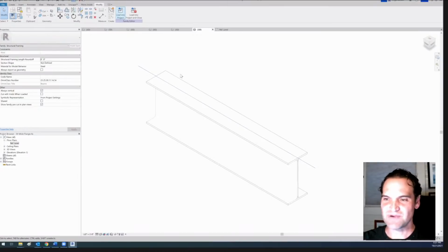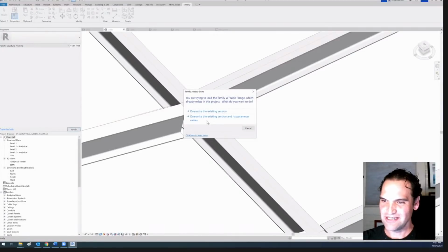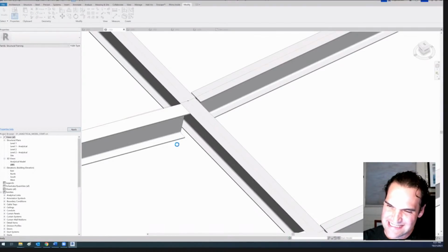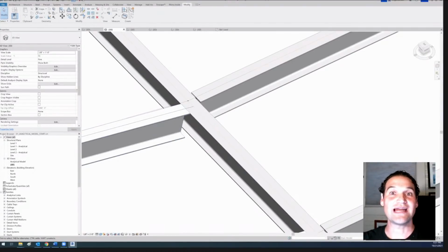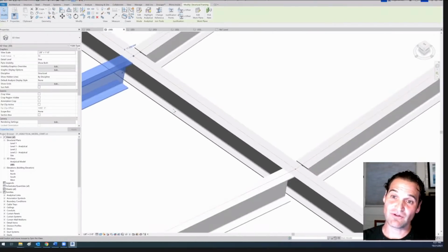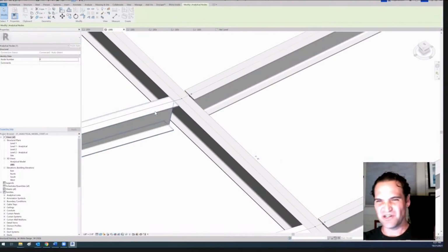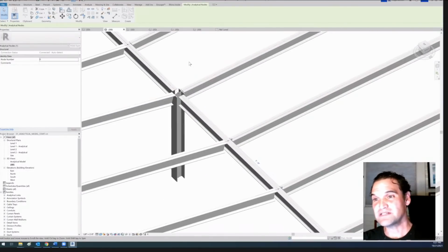I'm going to load this right back into where I was, which I think would be there. And now look, I have a center line that I can see right there. When I align it, now I have a center line I can align to. So I just aligned that beam using the analytical adjust, as well as putting in my own beam. Then you can unload them or turn them off with visibility, but you can leave the center lines on too, if you want to.